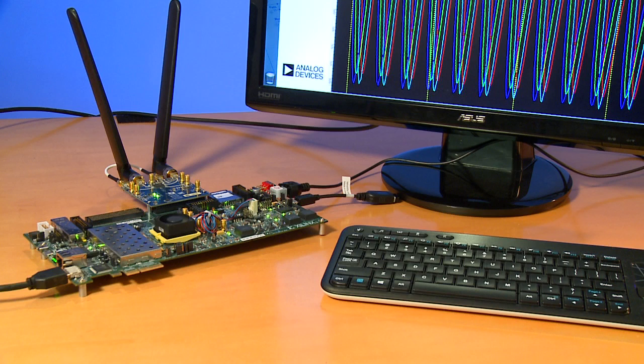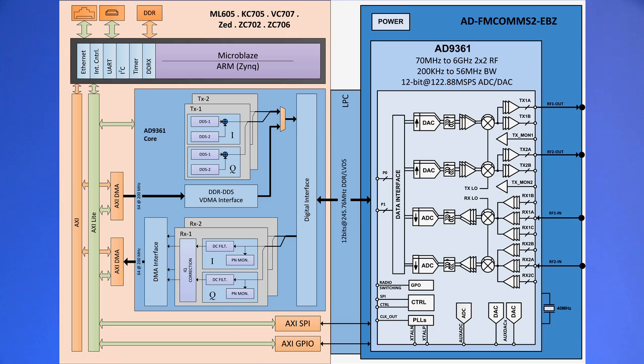is attached. Analog Devices provides a reference design for the Xilinx Zynq, which includes the HDL and the Linux device drivers for the 9361, plus a Linux user space application which runs on the dual ARM Cortex-A9s inside the Xilinx Zynq. Our reference design includes a few DDSs to create some continuous tones as test outputs, has the ability to stream patterns from files, and capture data from the receive side.